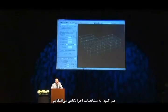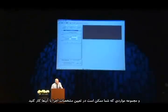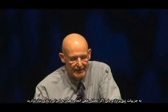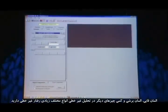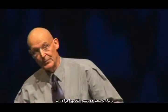I'm just going to look at component properties for now, and I just want to show the sort of things that you might have in the component properties. You have quite a number of inelastic components available. Again, don't worry too much about the details, but if you're in a linear analysis, you don't usually need very many components: a frame element, a shell element, and a few other things. With nonlinear, though, you have lots of different types of nonlinear behavior, and you find you need a much wider choice of components.